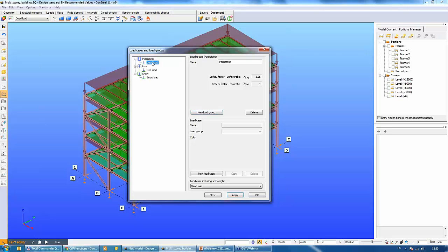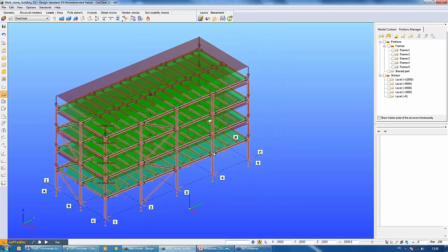And if we select one of the load cases, you can see the convert to mass option was deleted from this dialog because it was moved to the completely new mass tab, where you can find all of the dynamic related functions. Okay, so we have a simple loading system with 3 different load cases.